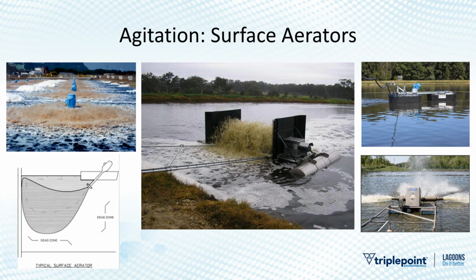These are relatively inexpensive from a technology standpoint. They're pretty easy to get out there on the pond. I've heard them described as like frisbees, just kind of throw them out there. But from a downside standpoint, you do tend to have a lot of motors that are exposed to the elements. And this is not necessarily the most efficient treatment technology out there if energy efficiency is of importance to you. So we'll look at that graph-wise later. But this is one of the more common treatment technologies. You see it out there quite a bit. It's very well tested, very well tried for the past 30 years, and it is a common aeration methodology.